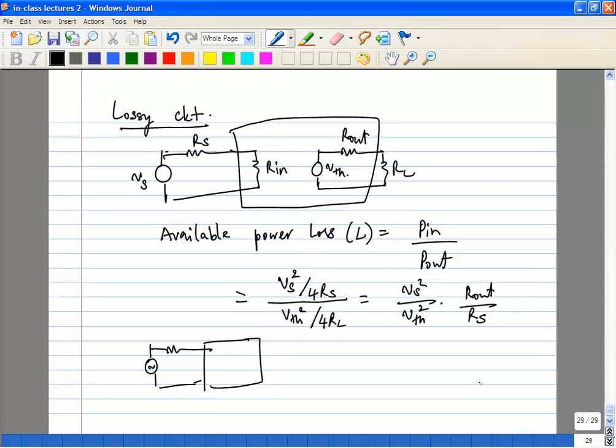If you have a lossy circuit, you want to characterize the loss rather than the power gain, right? So typically it's called the insertion loss. You insert a filter inside a receiver, and they'll tell you that it has a loss of 1 dB or 2 dB. I think we studied an RF switch. In some cases, like a TDD kind of system, you need an RF switch, and they'll tell you the RF switch has a power loss of so many dB. That's the reason you would rather characterize it by power loss, and you'll see why, because the noise figure is closely related to the power loss.